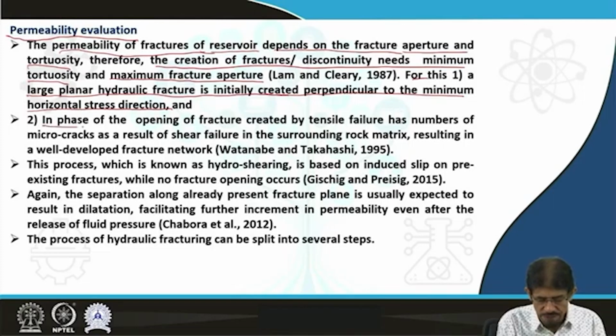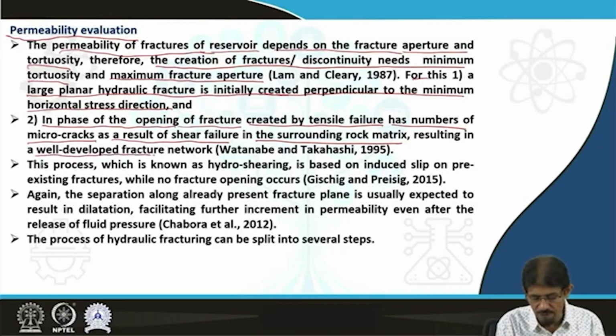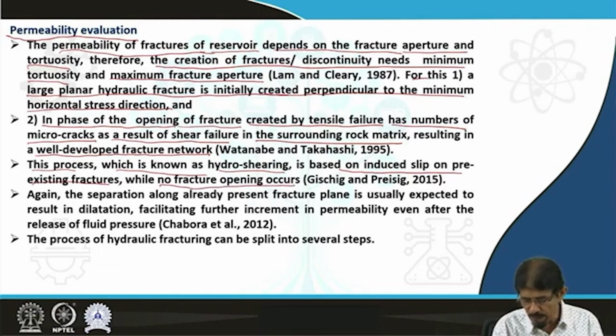Second, in the phase of opening of fractures or discontinuities created by tensile failure, there are a number of micro cracks as a result of shear failure in the surrounding rock matrix as well as in the grains, resulting in a well-developed fracture network that is going to help in extraction of geothermal energy. This process, which is known as hydroshearing, is based on induced slip on pre-existing or inherent discontinuities while no fracture opening occurs.